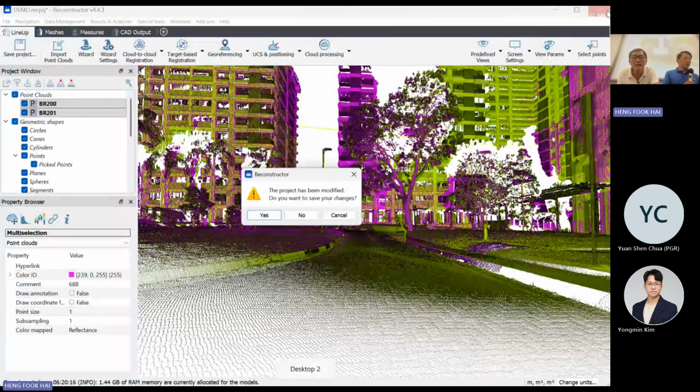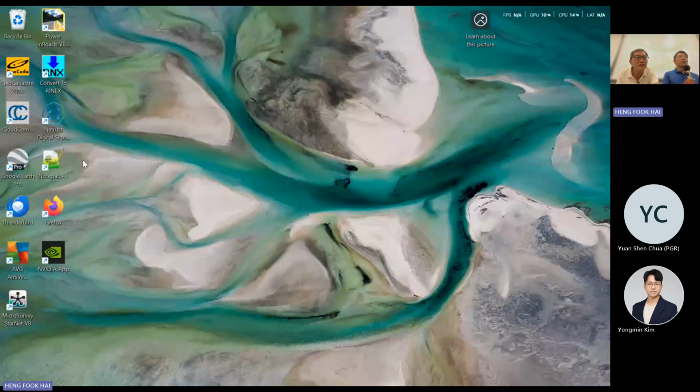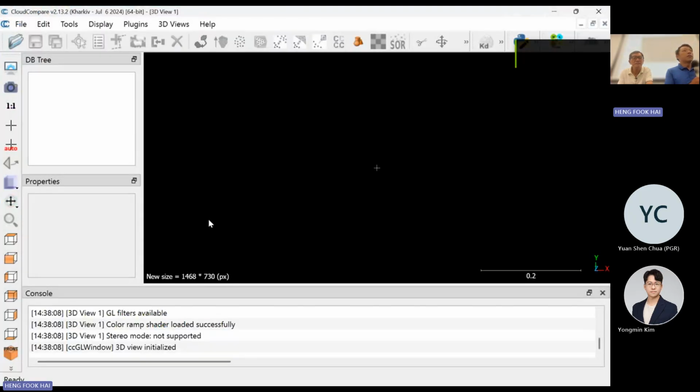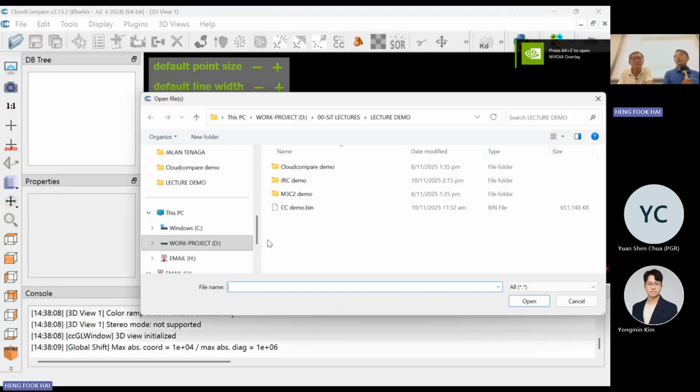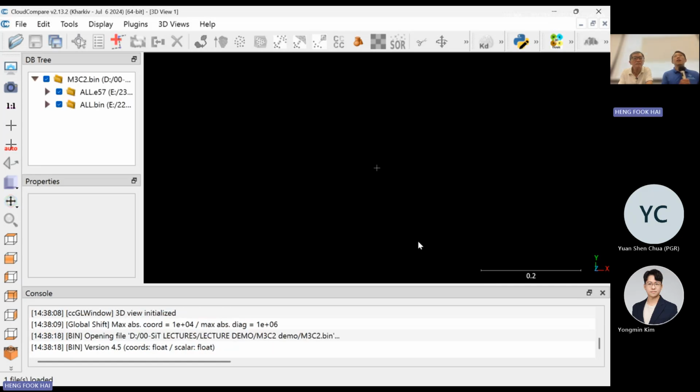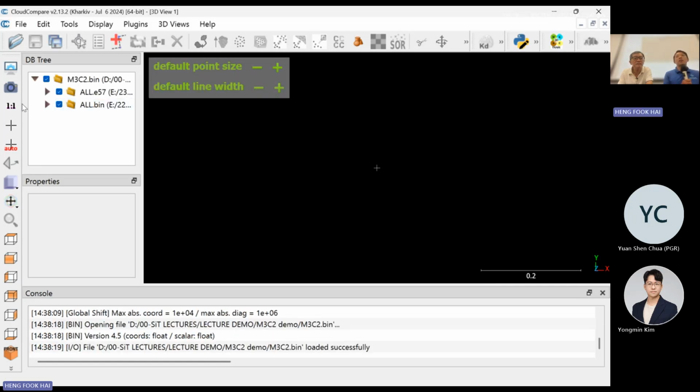So I think for engineers, a lot of times in deformation studies, what do you do with monitoring data? Most of our decisions actually come from the survey data that we receive, and then from there we try to apply some kind of engineering judgment to make the next step, whether to stabilize the slope, or whether we can just leave it and wait for further movement first.